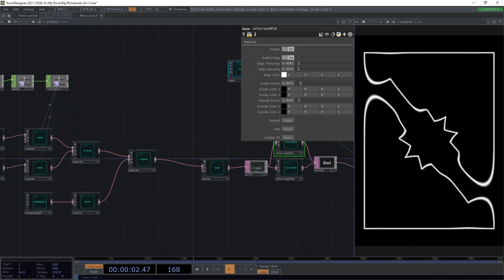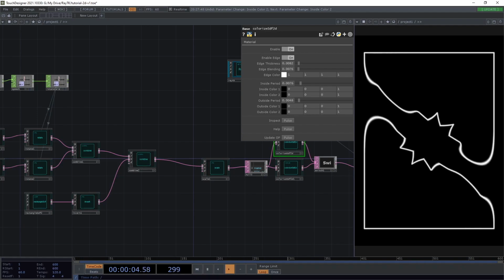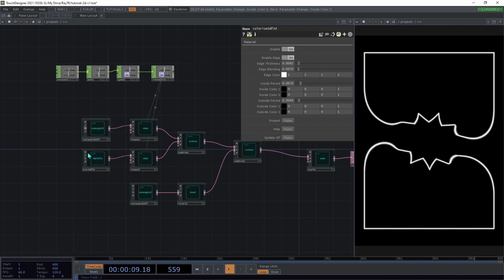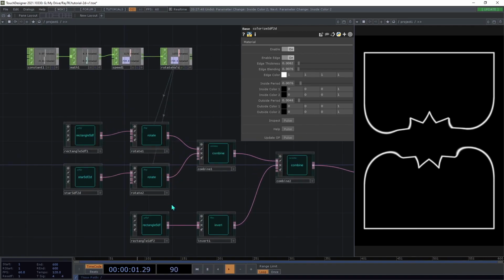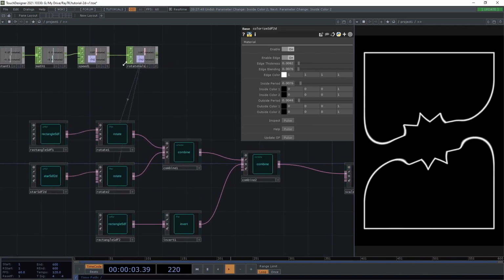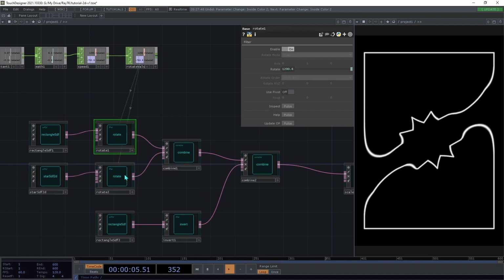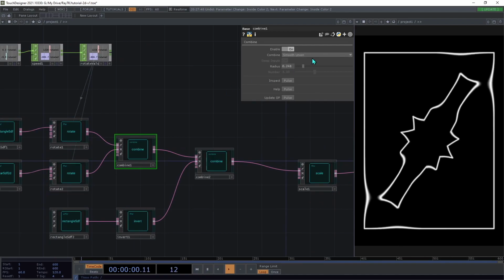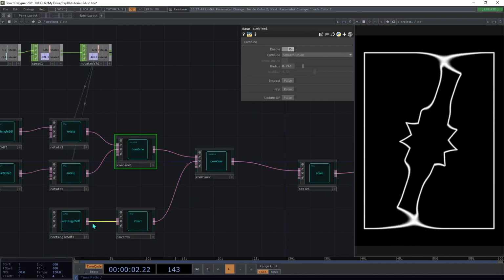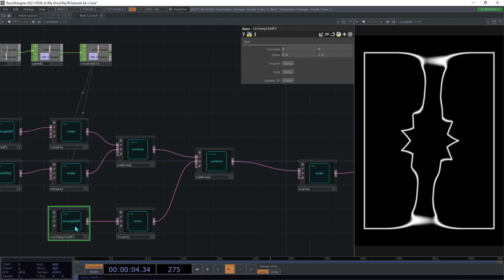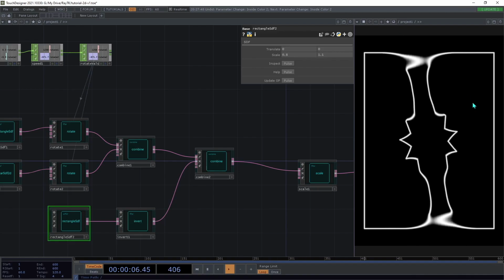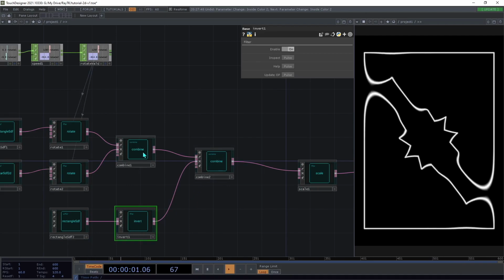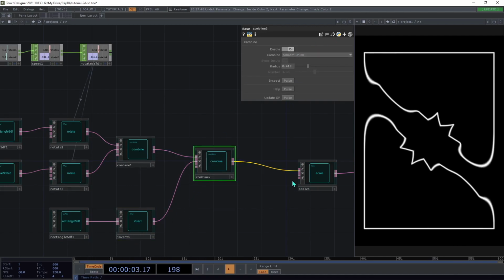So this is a basic version of the scene where you've got these two different 2D SDFs. They're each being rotated separately. Got those two rotation settings animated using these CHOPs. We're combining those using smooth union. Then we've got this other rectangle that's the outer frame, and we're flipping it inside out, and then combining that with that shape. I'm also using smooth union.